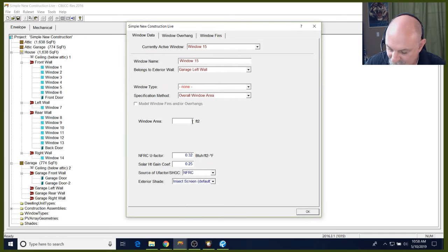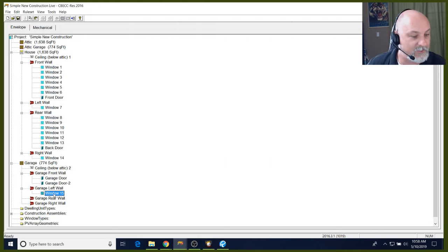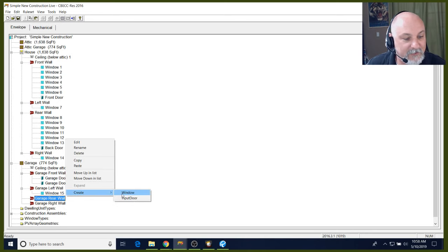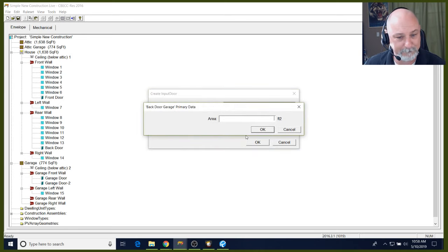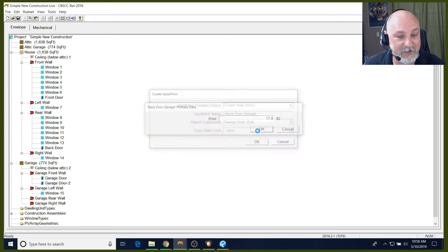I had a comment from a plan checker who said, your window area is too high. Well, look, it included the garage windows. Has anybody ever gotten that comment from a plan checker? You might want to point out, sorry, I can't type and talk at the same time. I haven't developed that skill. You can show them that those windows in the garage are associated with garage walls, and they can subtract that from the overall glazing, and it's not included in your glazing area.